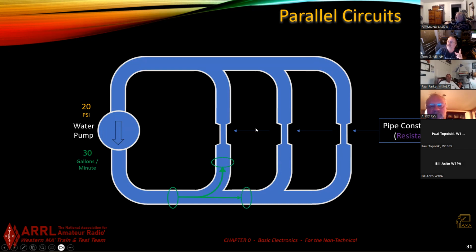So it happens that I've got one constriction here versus two downstream. About a third of them are going up the first pipe, and two-thirds are going to continue on down the line. And about a third of them are going up that pipe, which only leaves a third to go up the next pipe. So you'd balance that with all different resistance sizing, correct?